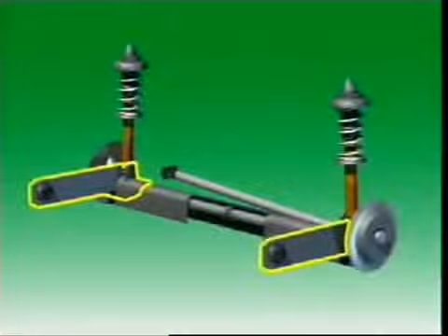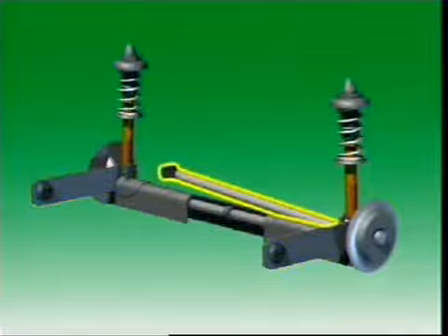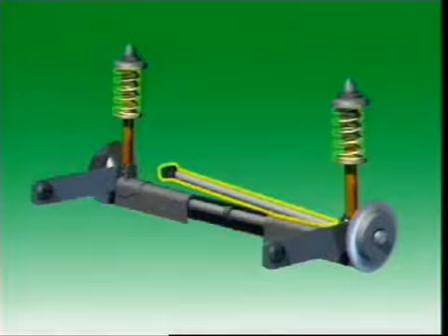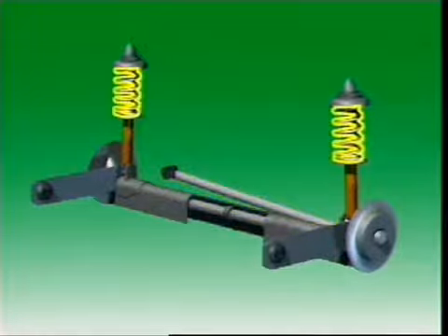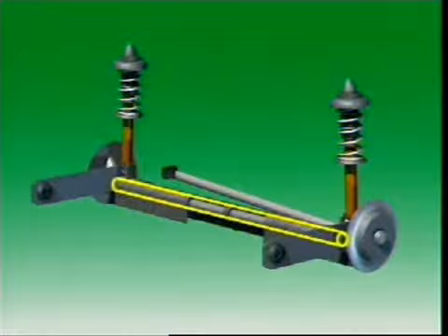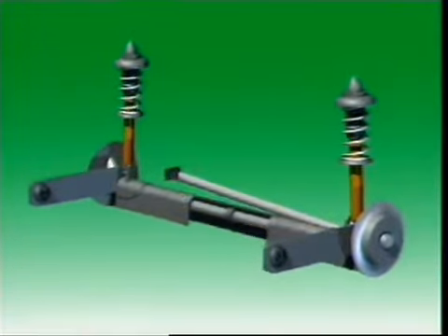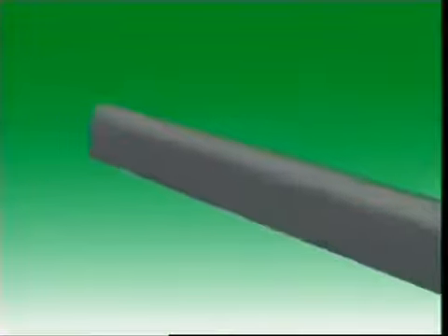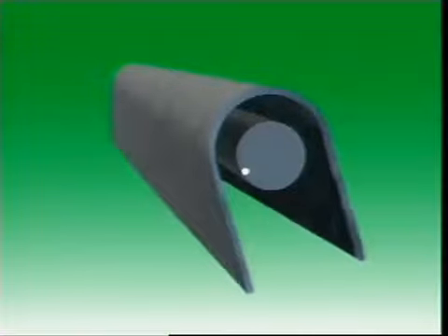This can be reduced by using a U-shaped axle beam with a torsion bar mounted inside it. Trailing arms are welded to the beam to locate the axle longitudinally. A lateral rod prevents lateral movement when cornering, and coil springs provide for suspension. The torsion bar is connected between the left and right wheel units, and deflection of the wheel on one side causes the axle and its torsion bar to twist together.